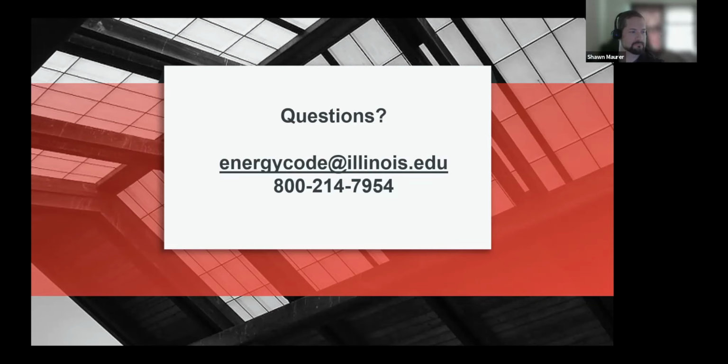Yep. And then a second floor addition. You're probably going to be replacing or at least adding HVAC equipment because you're adding square footage to the home. So the IECC requires that in renovations any new areas, so the whole second floor addition, but also the new mechanical equipment, will have to comply with energy code. So you will have to do a Manual J for the new equipment.